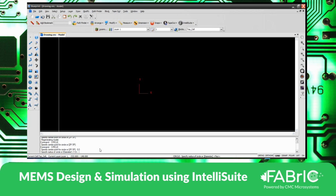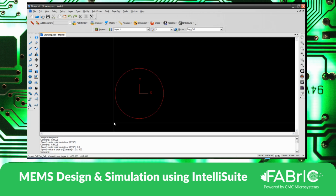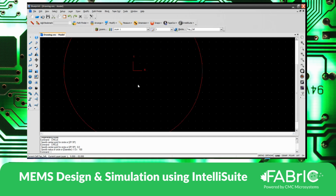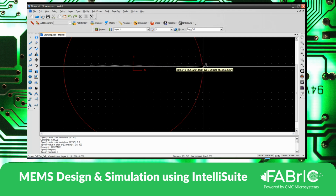If I write the radius outside the brackets, then it is a radius. If I write within the braces, then it's a diameter. So I wouldn't use that. I just say 100. So now the radius is 100. If we measure this, it should be 200. So diameter is 200.